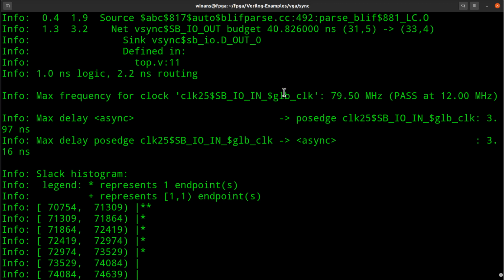However, I would hope that I could do better than this. Now, it may be that I told it it only needed to run at 12, which is like a default thing. I should set that. I've got to look up how to do it. I forgot earlier today when I was playing around with this. But this is pretty important, to make sure that that number is always greater than the clock speed you really want to run it at, because it will not work if you exceed this. You can load up your circuit with so much junk that it takes so long to do what you're asking it to do between clock pulses that it can't really function at even, say, 25 megahertz.